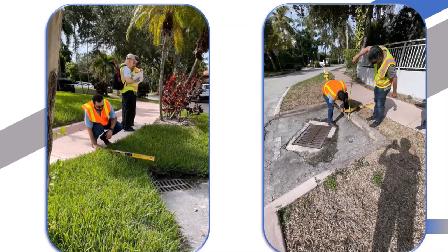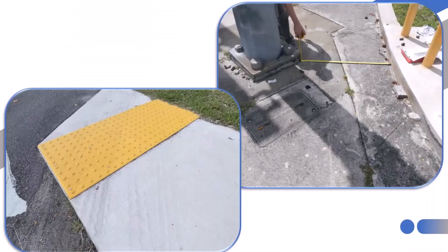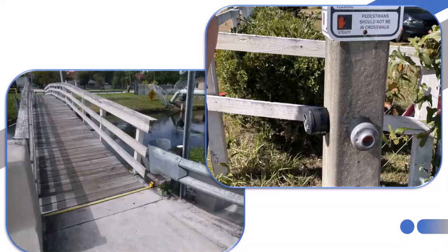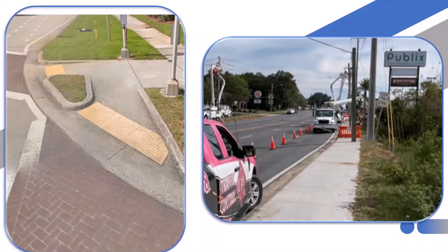drop-off protection, that's covered in the FDM Chapter 222 and in the Green Book. Look out for your operational safety issues. In the case on the left, you can see that vehicles are overrunning that detectable warning surface. Watch out for your horizontal unobstructed clear widths. That would be measured between the railings in the case of the boardwalk there over that drainage canal. And single finger buttons are no longer considered accessible. So you'd have to have the modern standard for that.